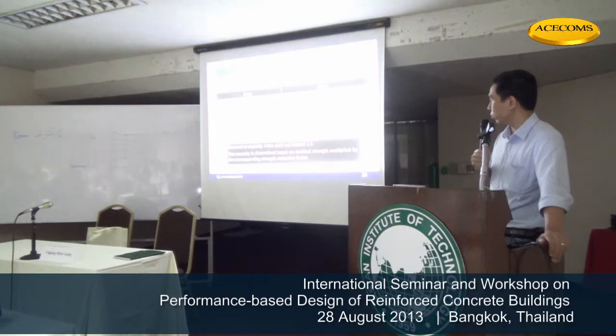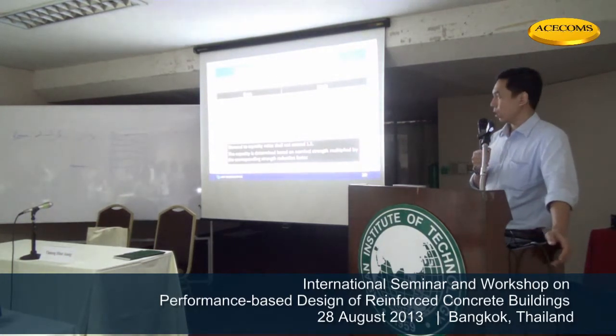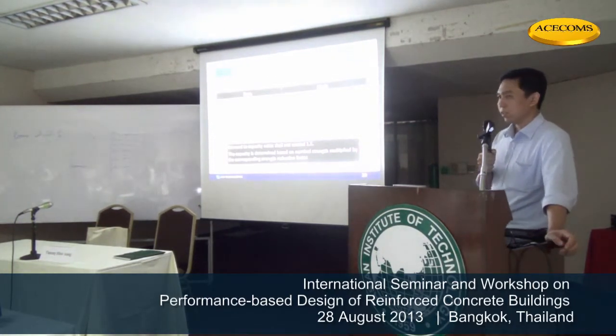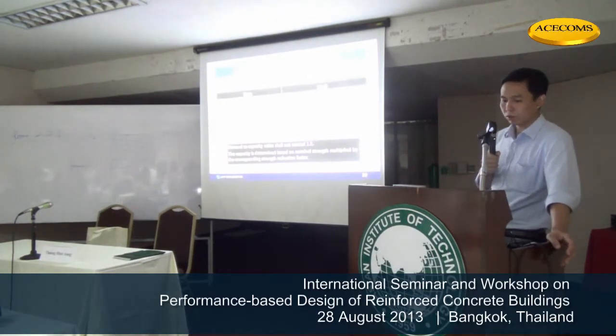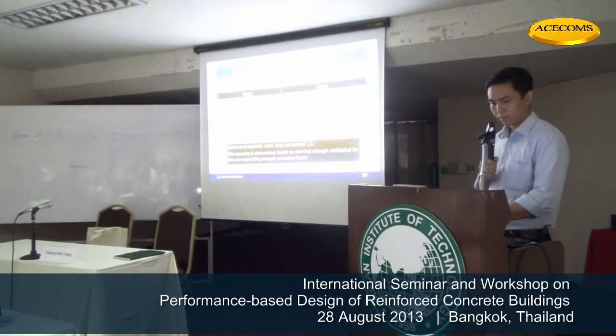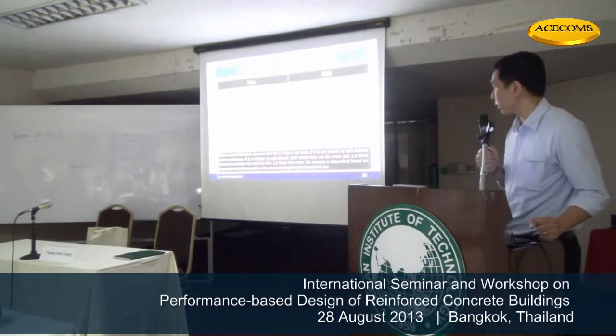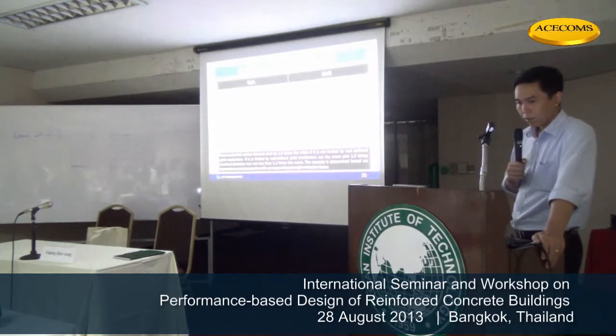So from the base shear results, when we check the seismic base shear for tall buildings, according to the equivalent static procedure, the base shear will be approximately 4%, 5%. The 4%, 5% is for a very high seismic zone. If the base shear is coming out very large, 10% in equivalent lateral load procedure, something is wrong in our modeling.